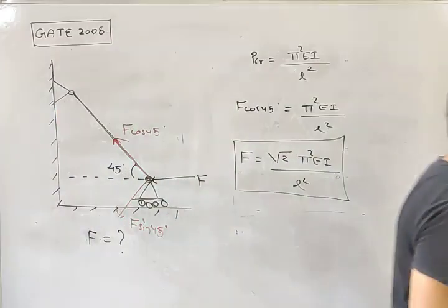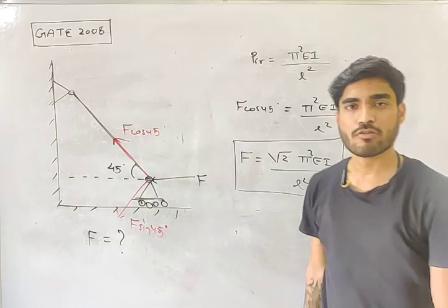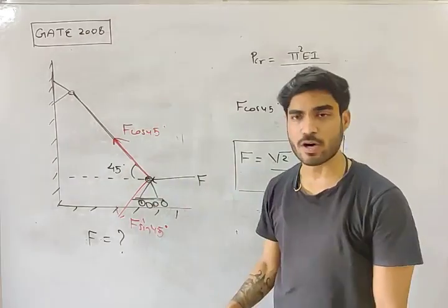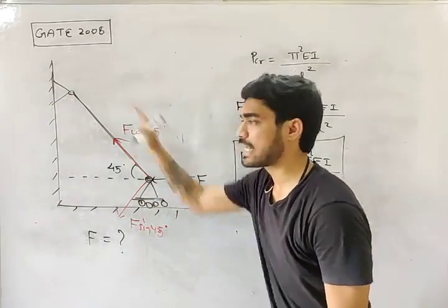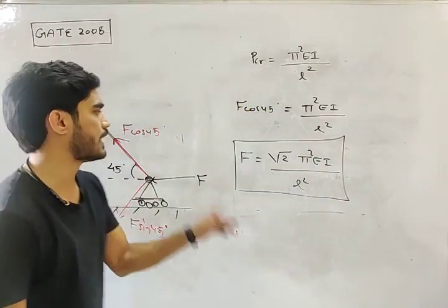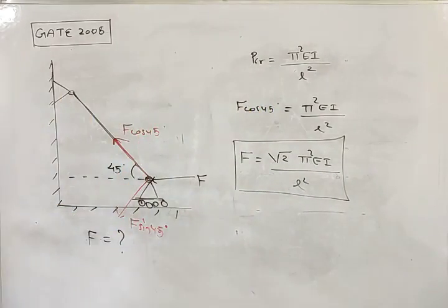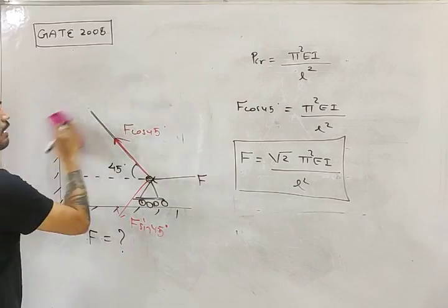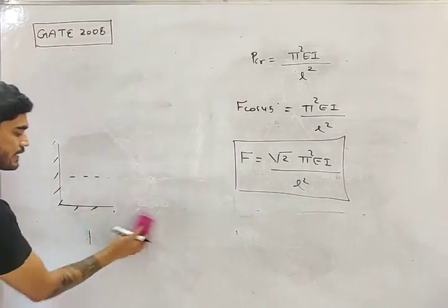So do you understand this question? If the load is inclined, what you have to do? Resolve the force and only consider the axial component. If the load is inclined, resolve the force and only consider axial component.